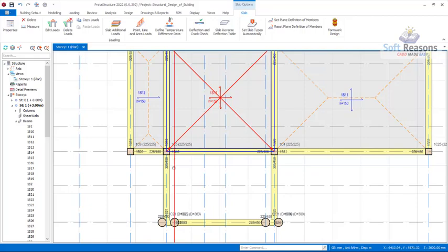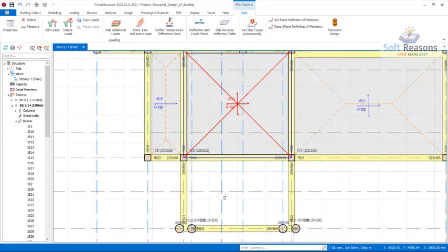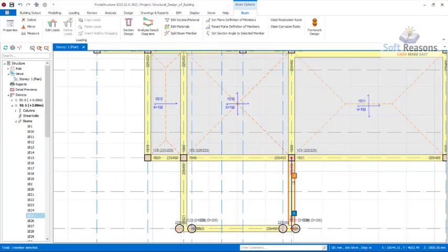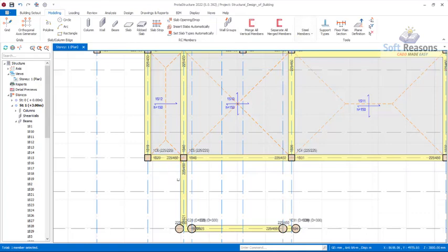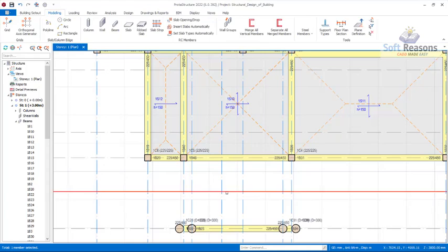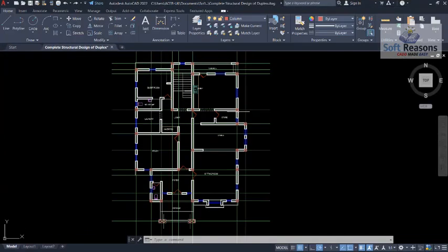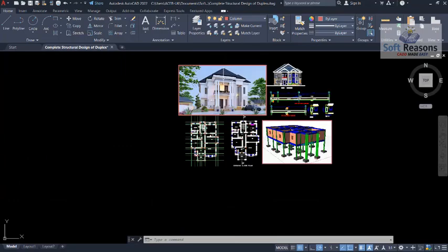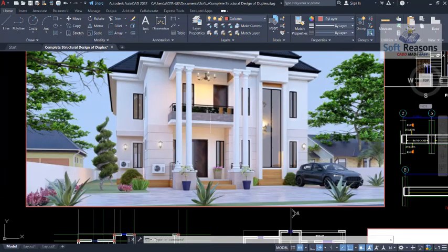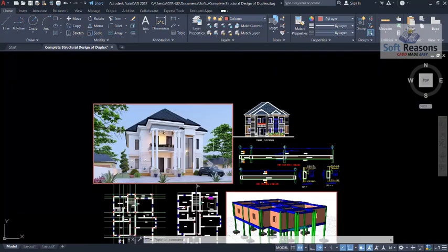Alright, so select this slab right there, right click, hit properties, use it here successfully, and then click on close. In this cantilever slab, I will show you how to apply a cantilever slab right away. We wouldn't need this beam, just as I've said earlier. Get rid of that based on the architectural plans. If you get back to the architectural plan right there, you will actually notice that we wouldn't need this beam. You can see here, this is a suspended slab. It is a cantilever slab, you can see it right there. So there's no beam connecting to it.